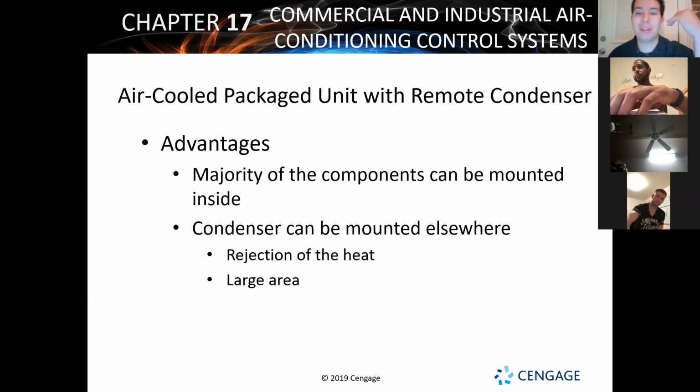The big advantage with this is the fact that you can have your different areas for heat transfer mounted separately and away from each other, and it makes life a little bit easier. And that's if you've got that remote condenser, and an air-cooled package unit with a remote condenser is pretty much a split system at that point. That's literally what it looks like.